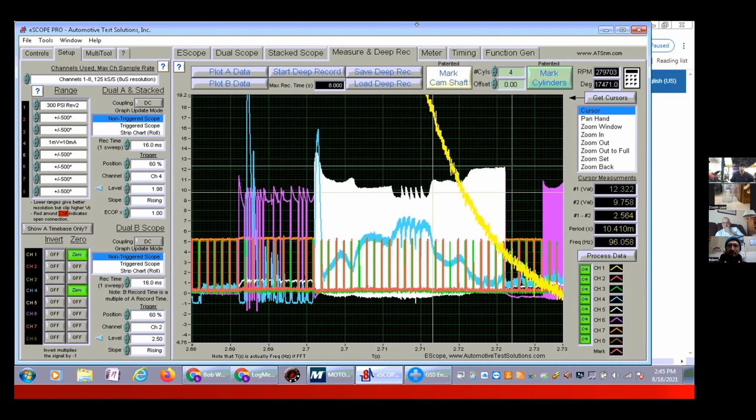Now look, some of the newer cars, as we know, are perfectly capable of calling out that individual circuit in the case of the extensions on the OBD2 codes. For example, P0136-87, that's a power circuit fault, right? Okay. Well, maybe if this was a 2019 car, we would have gotten that kind of indication out of it to point us right into the motor circuit. In this case, we didn't have the technology in this car for the computer to figure that out on its own. And we had to go in and diagnose what was going wrong with this thing, because quite frankly, we didn't know if the motor was causing it, the driver, a shorted wire, or what.